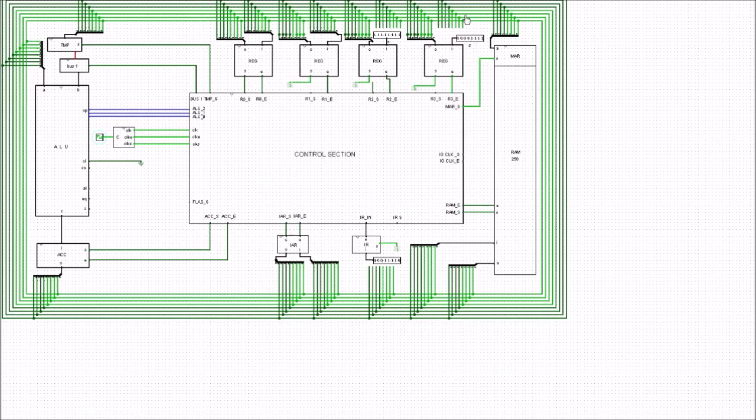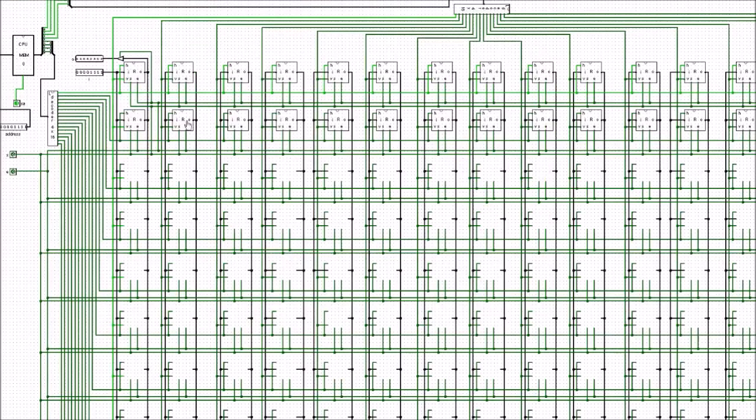So we've put that address onto the bus, and then we put it into the memory address register. So if we come down into the RAM, you can see here that the vertical line has gone live here, and the horizontal line has gone live here. So we're choosing this memory address location, which is memory address location 15.